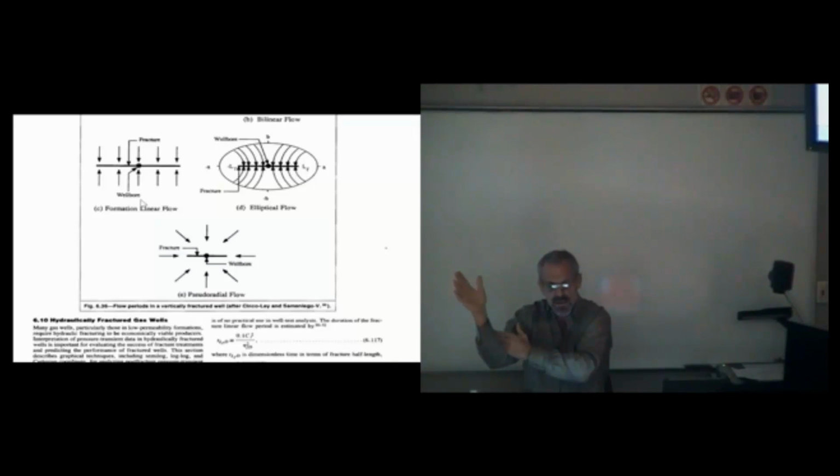And that means our derivative should be flat, start to flip up, and then go flat again. There should be a second semi-log straight line. We don't have that in our data. So we're going to assume that it's a confining boundary all the way around, and we'll calculate gas in place from that. If it did have that subtle lip and have a second straight line, we'd see it on the drawdown plot as well.